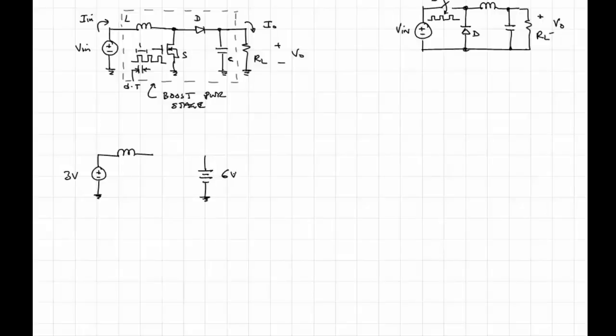And of course, if I were to just connect, let's say I put a resistor and I connect the voltage source to this battery, I'm not going to get any charging, right? In fact, what I'll get is the current going to my output here will be less than 0, right? And current will actually be flowing out, and I won't ever be able to charge my battery.